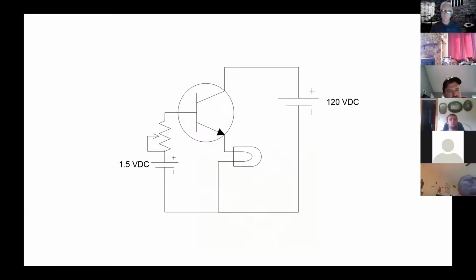Sometimes you use transistors as on-off devices, switches, transistor switching. But maybe the real value of a transistor is that you can regulate the flow, you can control the flow of emitter collector current. So in that way, this acts a lot more like a valve. We talked about the diode like a check valve. This acts like a regular valve. So if I have this turned way down to where not much current can get through, this current is very, very low, then this current also is low. And so the load is operating on low current.